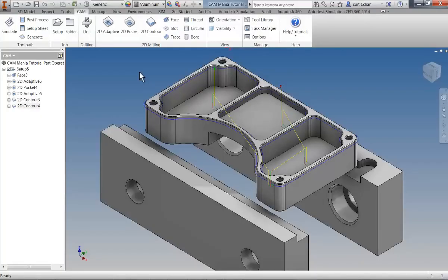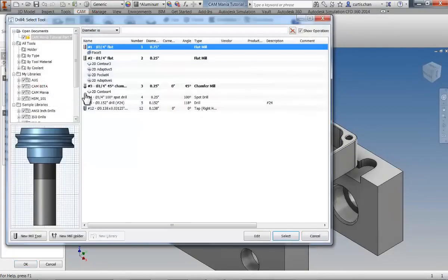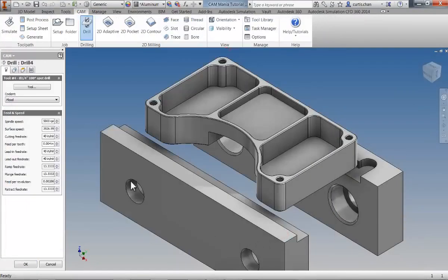We're almost done machining the part. The last task is to machine the holes. For this example, we want to machine 4 6-32 holes with a spot drill, drill, and tapping operations. Let's get started. Click the drill icon, open the library, and select the 1/4" spot drill.